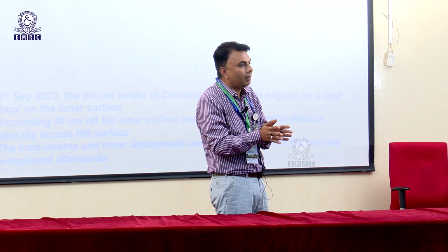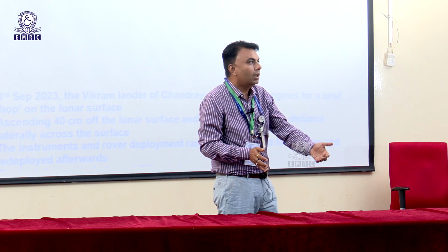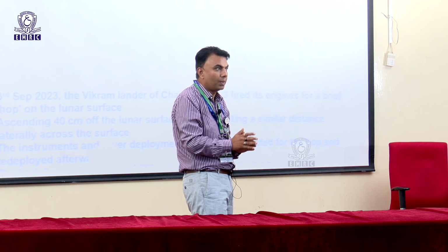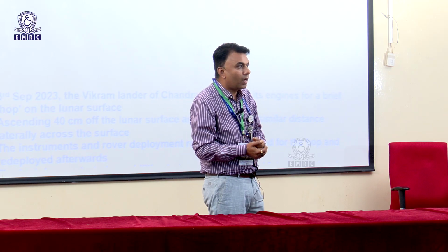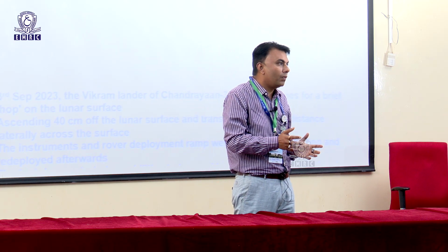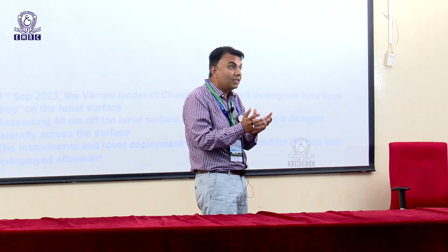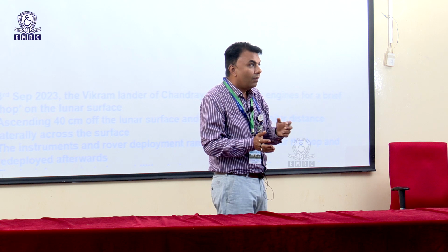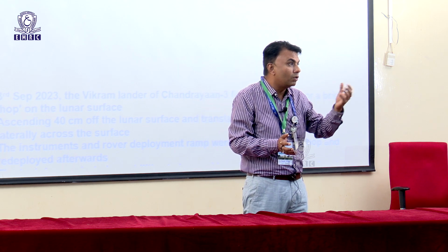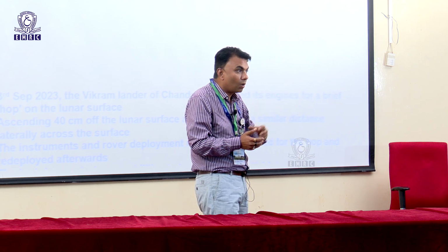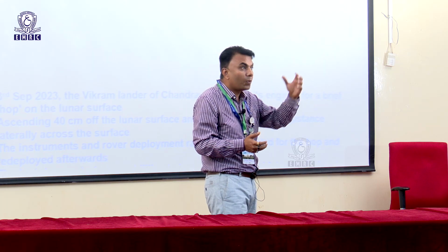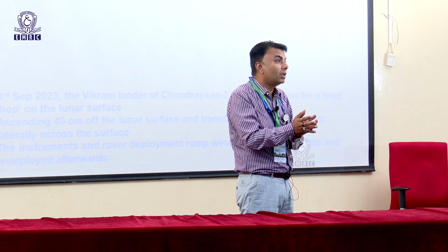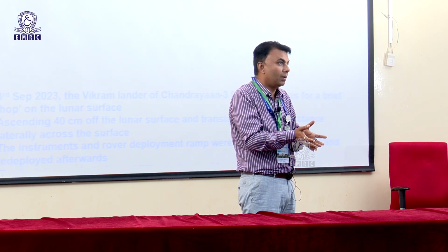And why are we having a better accuracy? Because we have an ionospheric local correction factor, which is not there in the case of GPS. That is one part. Second part, as a student, what can you do? See, as ISRO, we build the satellite, but better receiver designs are needed. These receivers are going to be used in practical life, where practical interference will come into the picture, like multipath, local ionospheric effects, and tropospheric error. So students can understand the local requirement, and based on that they can participate in the modeling of the atmosphere.